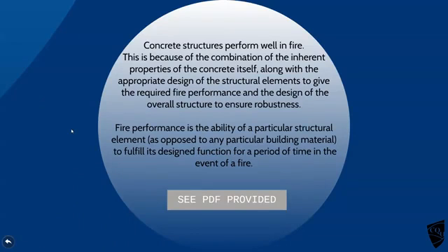They perform pretty well in a fire. Reinforced concrete structures are not too bad in a fire, but as the bloke was saying, it depends what temperature they got to, and the amount of cover, of course, because if you take off the surface to see the colour change and how deep the effect has been on the element, if you've got a lot of cover and it's a big section, then there's a lot of it inside, like timber really, which won't be affected. It would have insulated itself to a degree. But generally, in the actual fire, they're good. But we found out that they lose strength afterwards.